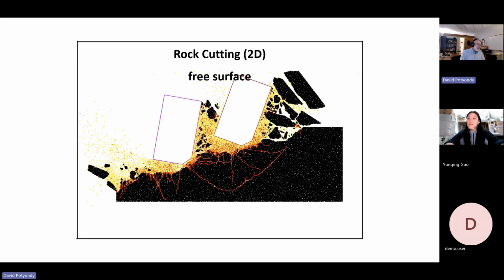Okay. And he had a very important insight. And he said, oh my God, I think I've understood something that we never understood. And I said, what's that? He said, well, turns out that this shape here is very critical. Very small changes to this shape, they call this a chamfer. You can see how it used to be 90 degrees and then they cut off this facet. And depending upon how deep you make this and depending upon this angle, it has a very big impact on the amount of energy required to cut.